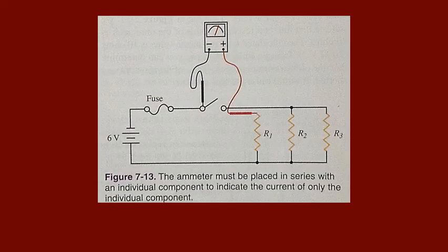In figure 7-13, troubleshooting a parallel circuit will become easier as we learn more about the current, voltage, and resistance characteristics. One factor that assists us in determining the best method of troubleshooting a circuit is determining how the circuit has been assembled. When a breadboard is used to construct circuits, troubleshooting is much easier than when the components are soldered in place, and we must first desolder to take the readings.